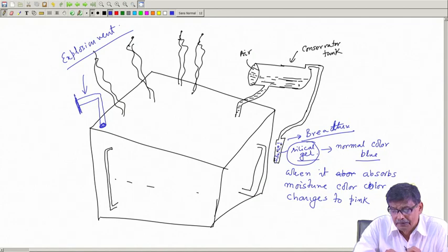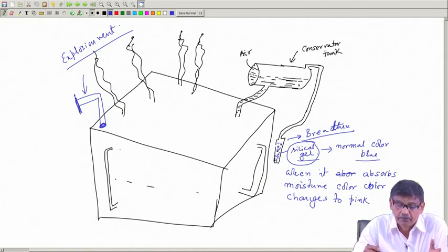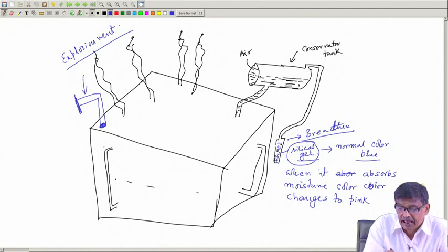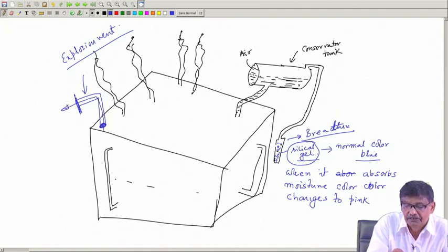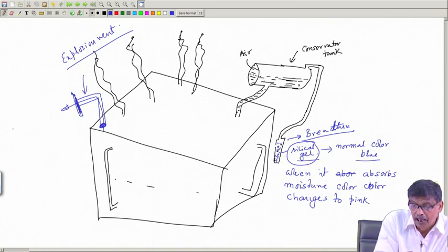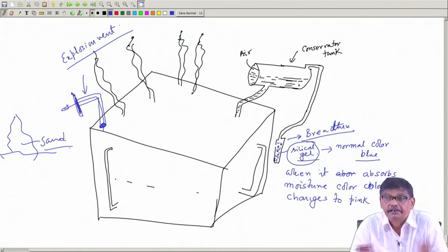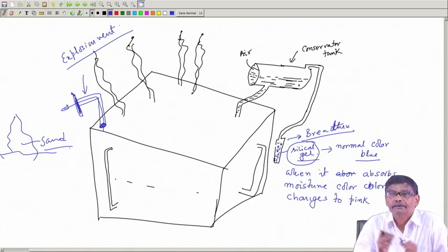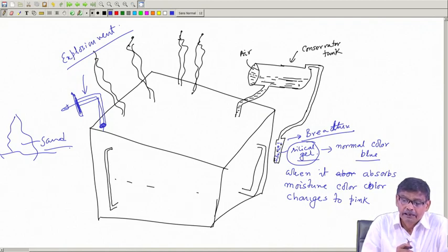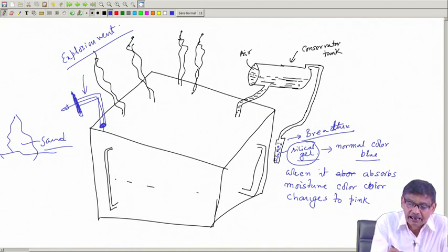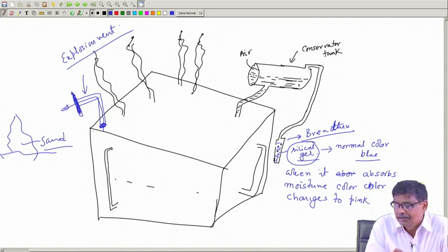So, oil pressure inside the transformer builds and it will break this, and this oil will gush out from this place. And the direction of this explosion vent is made at a particular angle, where you will keep sand, etc., so that fire does not break out, because that will be very hot oil and it causes fire. Got the point? Therefore, explosion. So, this plate diaphragm is also weak, this is also weak.